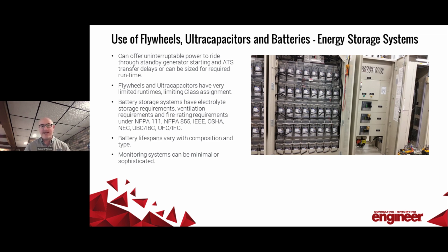Additionally, it's always good to note that if the supply system wants to be uninterruptible, for example, battery replacement and maintenance should be taken into consideration. So am I going to lose the entire string if I replace batteries because they all have a specified amount of life? That's for the engineer to decide. And you're going to want to take that into consideration where multiple battery cabinets can sometimes solve those problems. We're not going to go into much more detail about this precise type, but I did want to at least mention that you have other types of energy storage that are within other sections of NFPA. So if you're curious about that, you're going to look elsewhere.